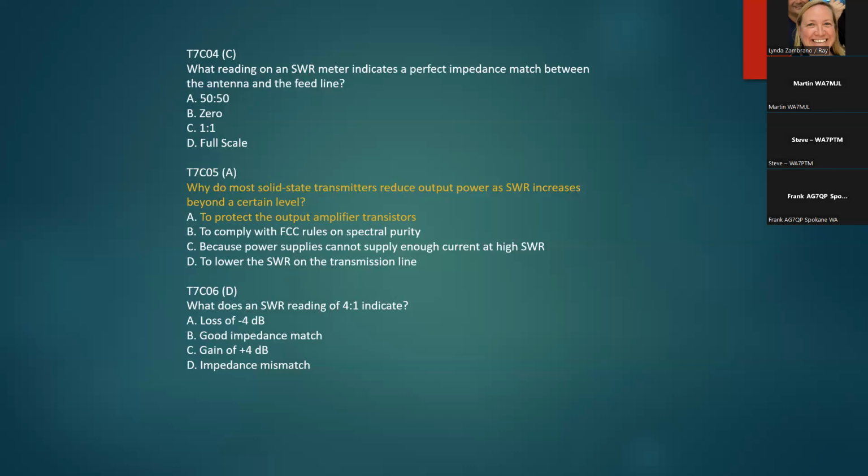Very bad and possibly a very expensive fix. So you want to make sure that your antenna and feed line are operating at a reasonable SWR, 1.2, 1.3, 1.4 in there.